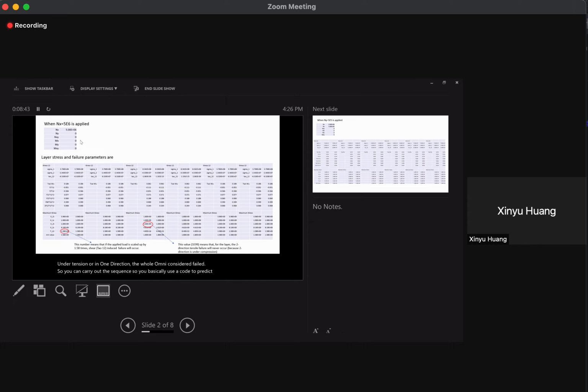When you do a laminate mechanical test, this behavior shows up in experiments. You can pull a complex layup. You can detect at a certain point, a certain layer gave up. But your laminate can still carry more load because load is carried by other layers. But you can detect a bend in your stress strain curve. Your stress strain curve is not straight anymore. It's a certain bend. And it can bend several times before final failure. And those behaviors can all be captured by CLT code.